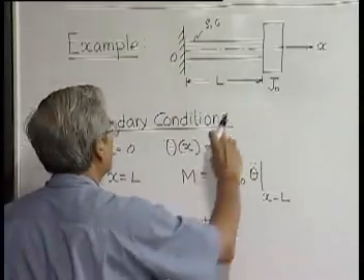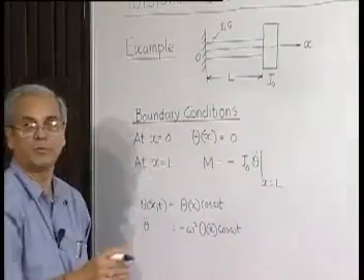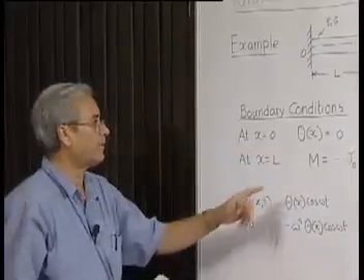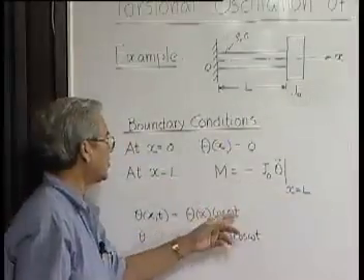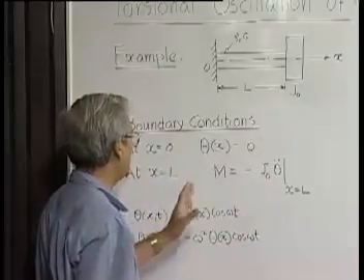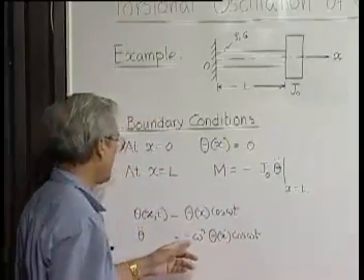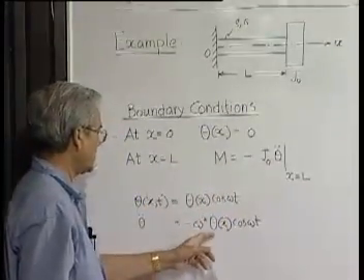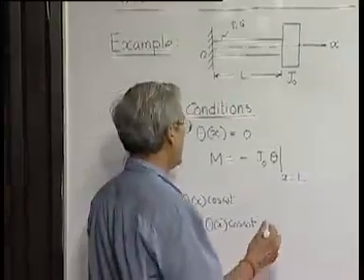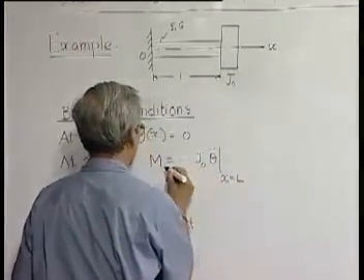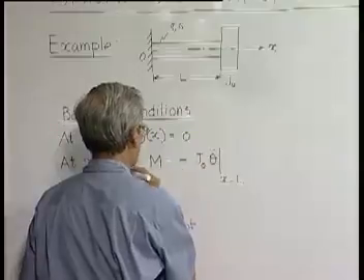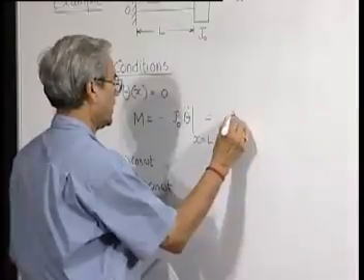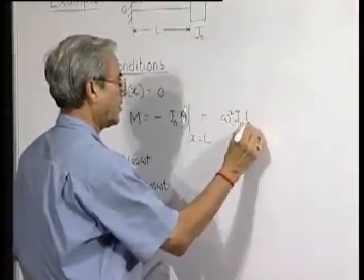So the moment which is acting here will also be a dynamic moment, a harmonic function of time into cosine omega t. So when we are dealing with only the magnitude of the moment, it will be minus J0 into minus omega square theta x. So you can say when we are dealing with only the magnitude, this magnitude will be equal to omega square J0 theta.